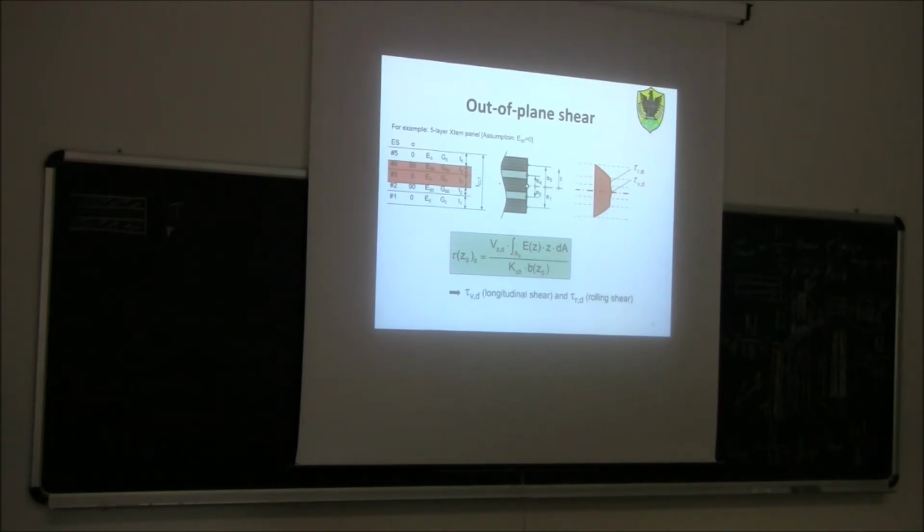If you think about the simply supported beam, on the support you have only shear and no bending moment. In the center, at mid-span, you have only bending moment and no shear. But in the structure itself, it's not possible to have a length of structure with, for example, only shear, not bending moment. In a cross-section, yes, but not in the length.